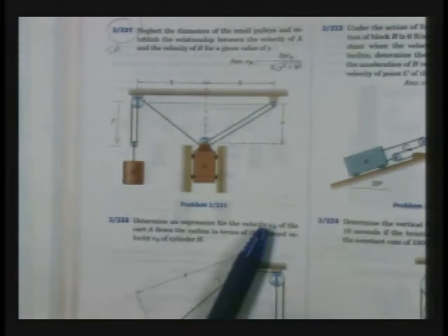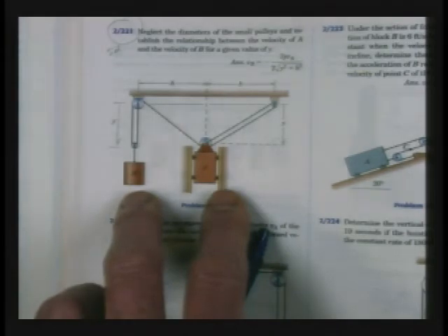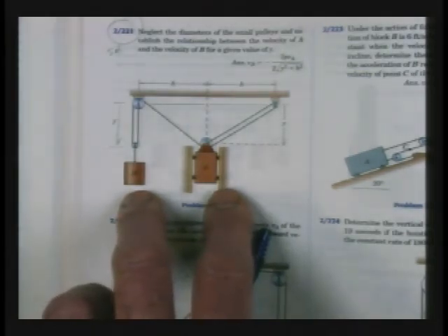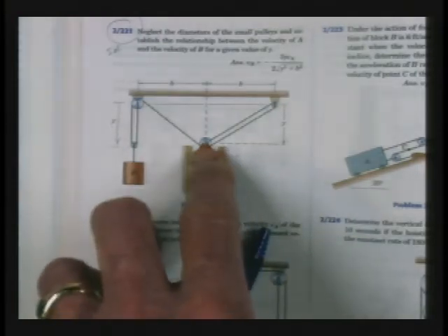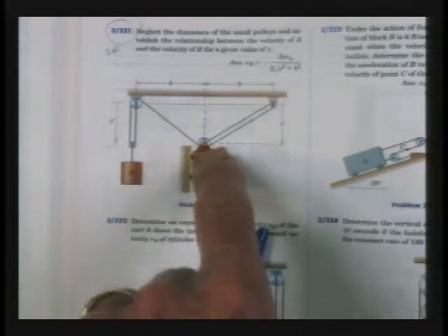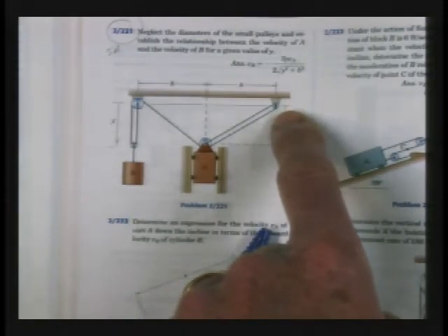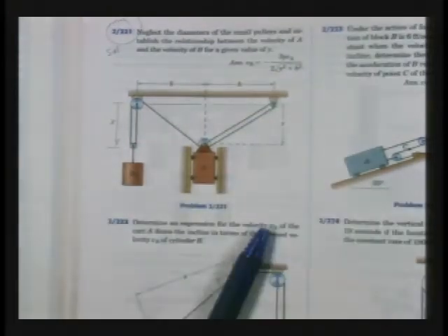But in the differential sense, what we're looking at is an instant, in a particular geometric configuration. At an instant of the motion, those are considered second order effects when you start differentiating. So the arc lengths from the changing tangencies, we can neglect in typical engineering fashion. There are applications where that behavior would be critical to take into account, but the analysis would be a lot more complex.